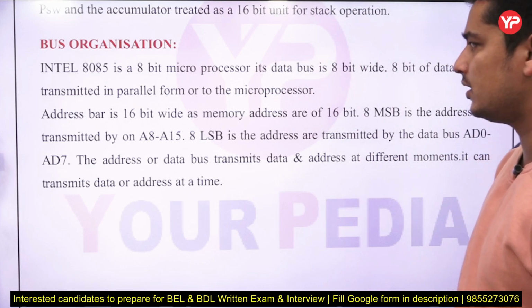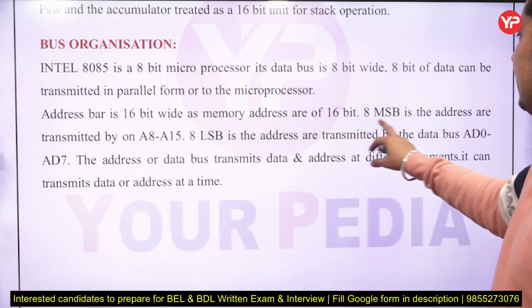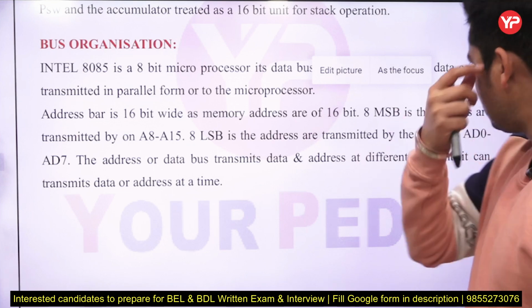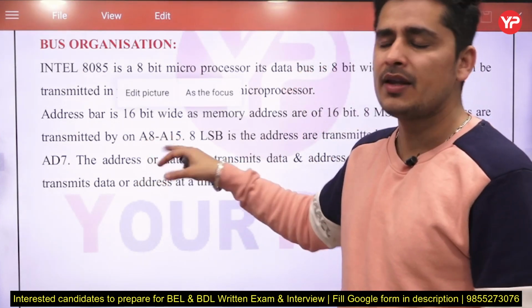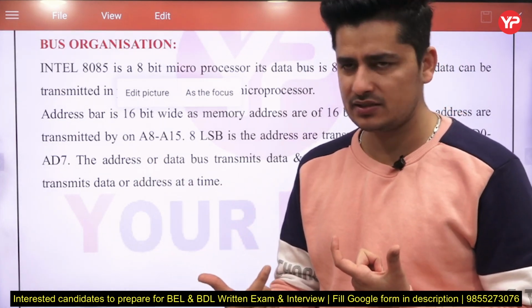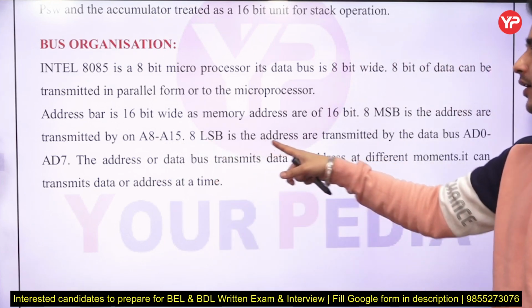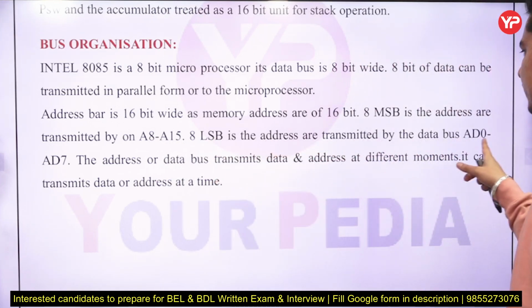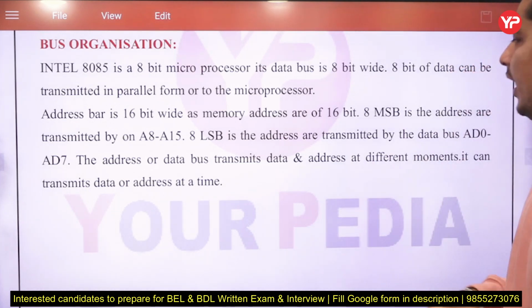The address bus is 16-bit wide, as the memory address is 16-bit. The 8 MSB address bits are carried by A8 to A15, and the 8 LSB address bits are transmitted by the data bus. I already told you that the data bus is combined with the address bus.